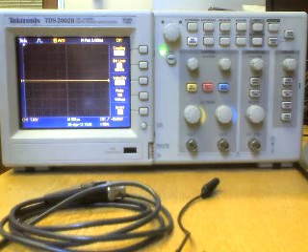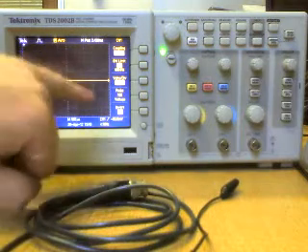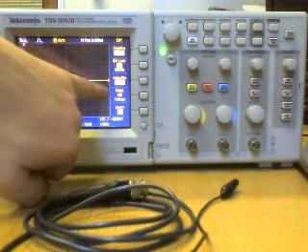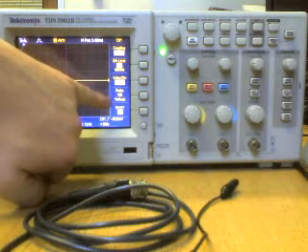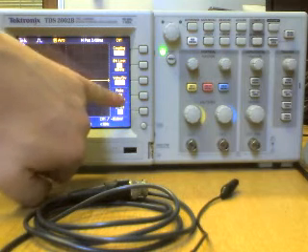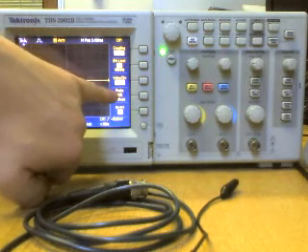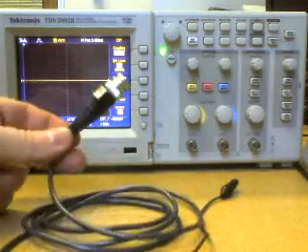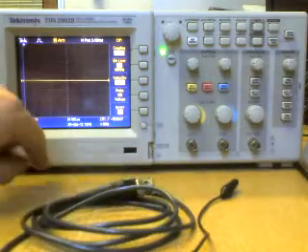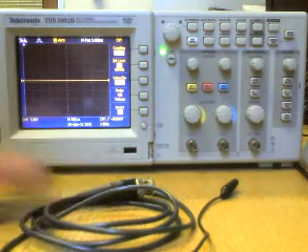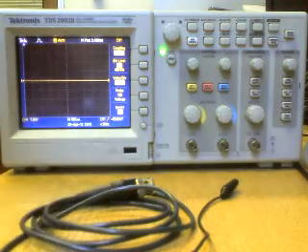But instead of you having to perform that mathematics, that multiplication, that division, we have here a probe setting called probe voltage 10x. Now this is saying that it's expecting you to use a ×10 probe. So if you plug in a ×10 probe, you don't need to do any of that multiplication or anything. That's actually done internally in the unit.